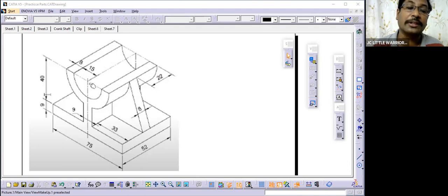That means there will be tight tolerances, so that they can maintain the relationship between this part and the other part, maybe that part is rotating. We are not sure in this diagram, but in that case this axis should coincide with the pipe axis, and this diameter should match with the pipe diameter, so that it can perfectly sit here. So this area should be designed properly.